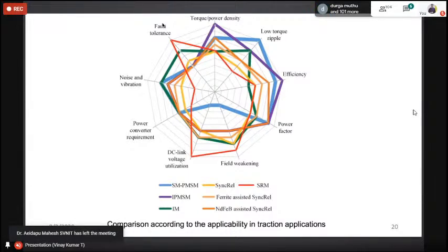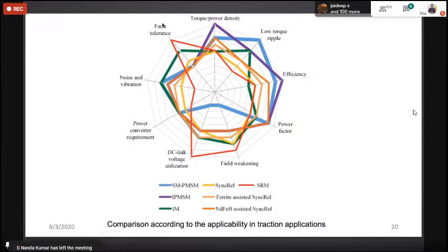Here you need to take concentric winding on the stator side. So the concentric winding advantage is that even if one of the coils gets a fault or gets open, by using the other coils also we can get continuity. We can continue to operate the drive.